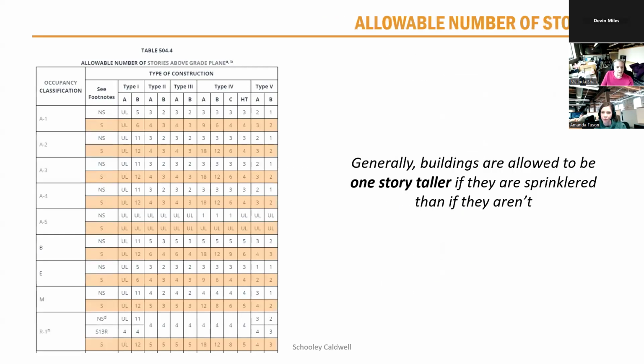Likewise, for nearly all building and use types, if you have sprinklers, that building can be 1 story taller than it would be before. This is also really helpful when working on old buildings that maybe were 3 or 4 stories tall, but under the current code provisions, with both that use type and construction type, would be required to be shorter than maybe what it is.